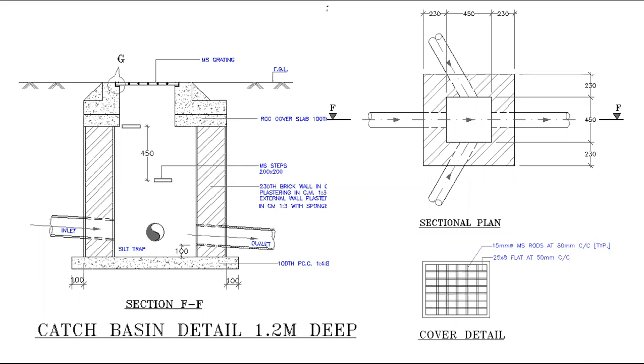They will collect it. After making the dosa, they again put some half liter of water into the dosa pan. It will go into that drain only, into our grease trap only. After finishing the shift, they will remove the grease or oil from the grease trap and throw it into the effluent tank. The effluent tank is a separate tank kept for effluent treatment.